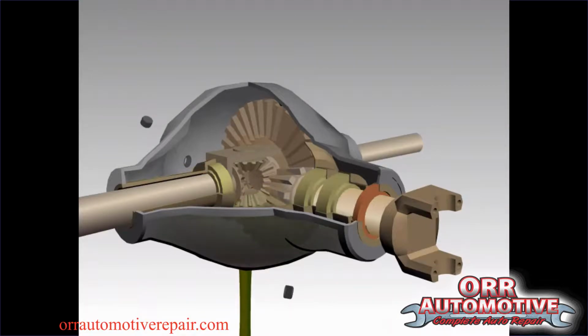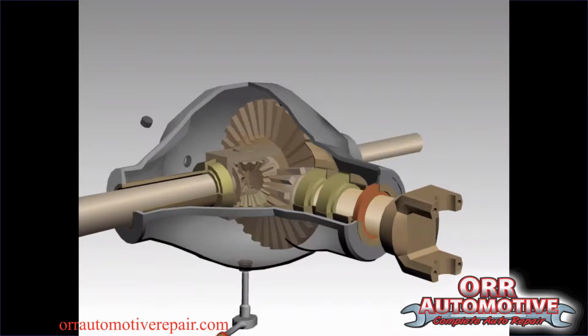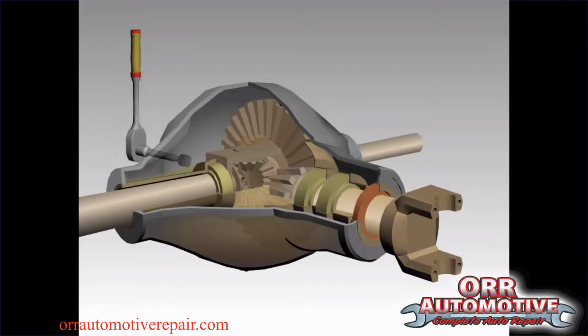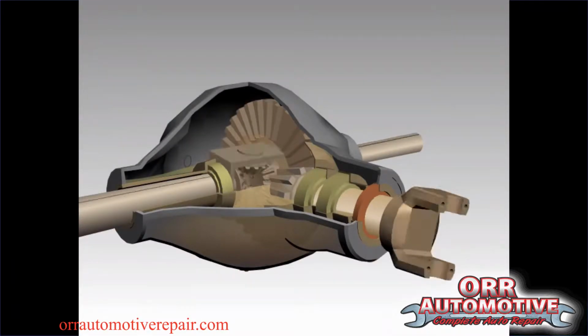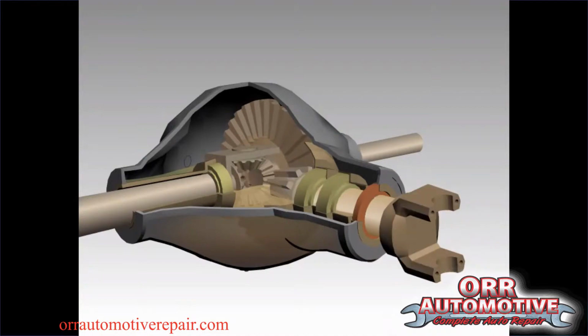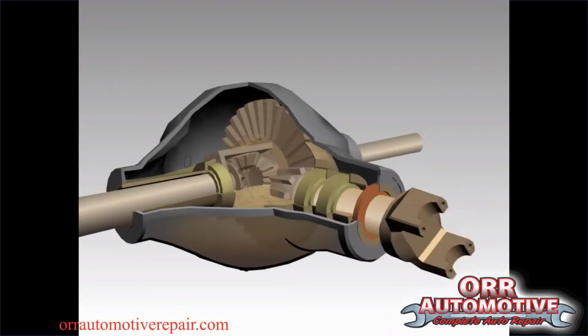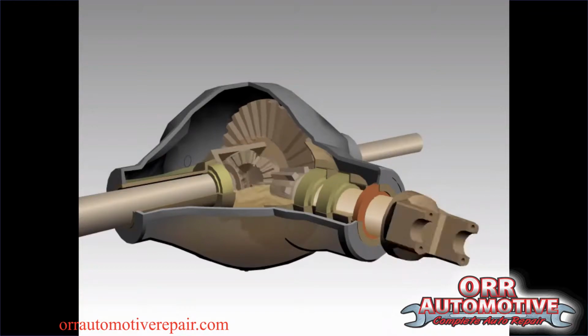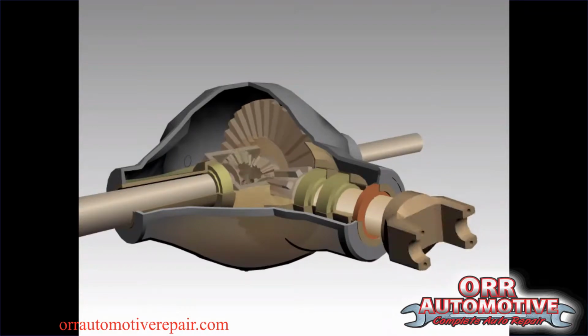The interval for heavy-duty vehicles is usually shorter, as towing or hauling heavy loads can cause the fluid to degrade more rapidly. When rear differential fluid is neglected, it leads to the breakdown of the gear oil and can cause the differential gears to wear, causing the differential to become noisy and eventually leading to the failure of the differential. A rear differential fluid service is significantly cheaper than replacing a complete differential assembly.